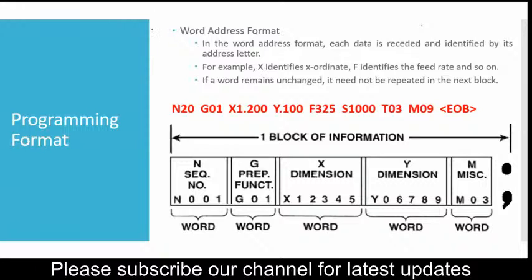Okay, if only you could say about T03, what does it stand for? T03 stands for tool number 3. If I write M06 T2, not the entire line, but just M06 T2, the machine will change from the current tool to tool number 2.